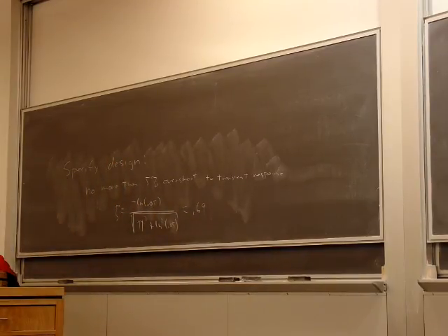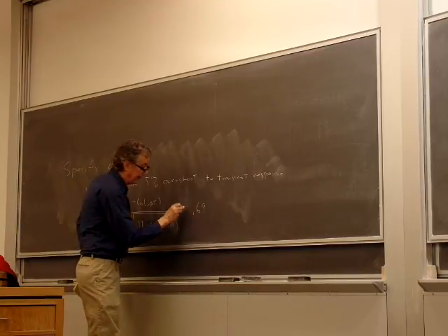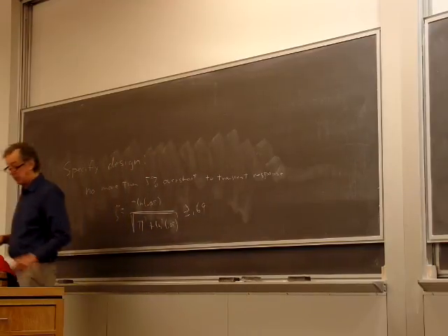So we have an inequality here. We want no more than 5% overshoot. So is the damping ratio 0.69 and bigger or 0.69 and smaller? Bigger. Bigger damping, less overshoot. So I'd like to have this thing greater than 0.69.